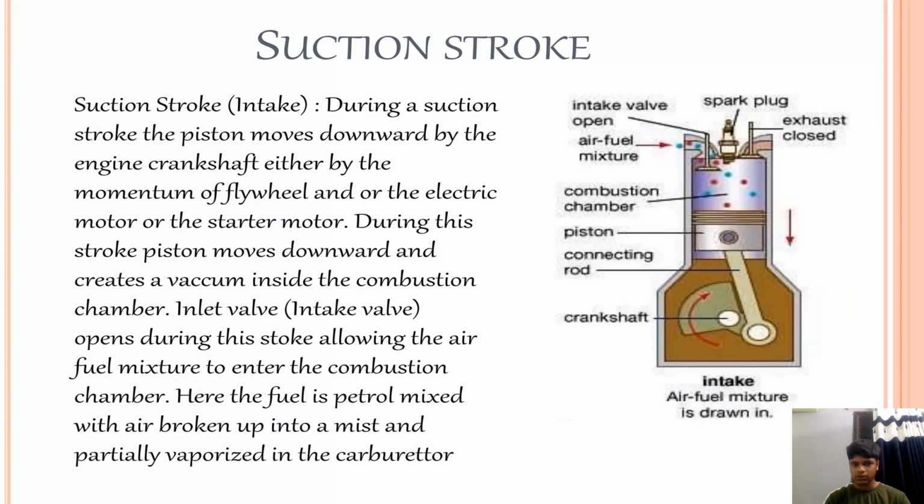Next, suction stroke. During the suction stroke, the piston is moved downward by the engine crankshaft, either by the momentum of the flywheel or by the electric motor or starter motor. During the stroke, the piston moves downward and creates a vacuum inside the combustion chamber. Inlet valves open during the stroke, allowing the air-fuel mixture to enter the combustion chamber. Here the fuel is petrol mixed with air, broken up into mist and partially vaporized